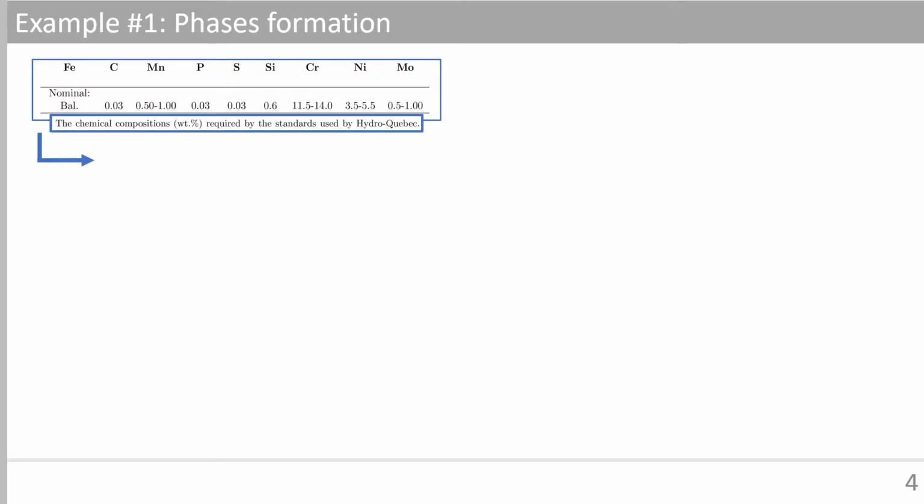Okay, so in this project, we are looking at stainless steel that contains some chromium and nickel. Chromium is there to protect the alloy and to form an oxide layer at the top of the stainless steel. Nickel is there to improve the mechanical properties of the alloy, and then we have some other elements that also ensure the desired characteristics.